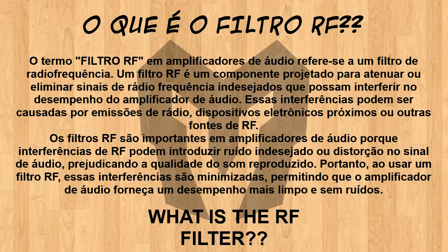An RF filter is a component designed to attenuate or eliminate unwanted radio frequency signals that may interfere with the performance of the audio amplifier. Such interference may be caused by radio emissions, nearby electronic devices, or other RF sources. RF filters are important in audio amplifiers because RF interference can introduce unwanted noise or distortion into the audio signal, degrading the quality of the reproduced sound. Therefore, by using an RF filter, these interferences are minimized, allowing the audio amplifier to provide cleaner, noise-free performance.